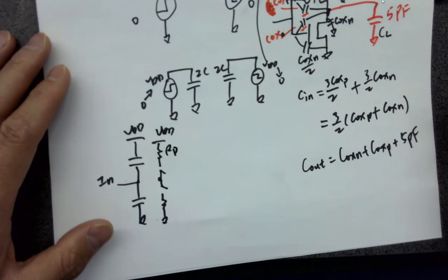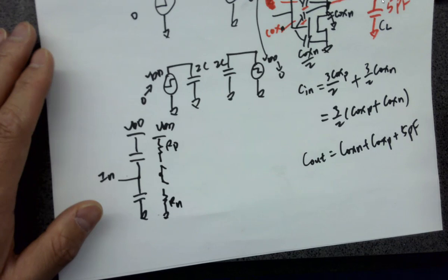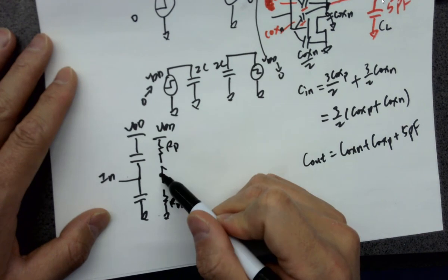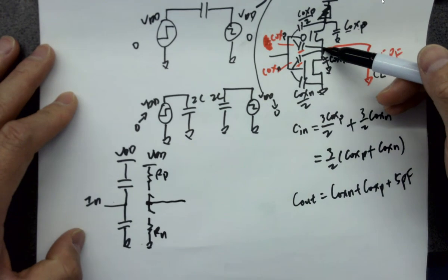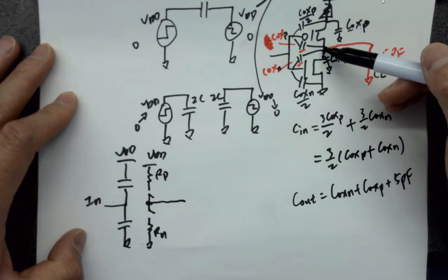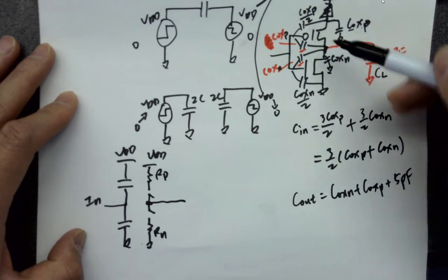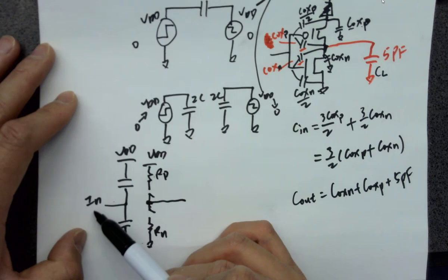This RP is the channel resistance on the top, and the channel resistance at the bottom is RN. And here you do have a connection, because it's at the same output node. The output node is directly connected to the channel because that's a source, that's a drain, right? The drain has a direct connection to the channel resistance. That's why the switch models the on-off voltage.